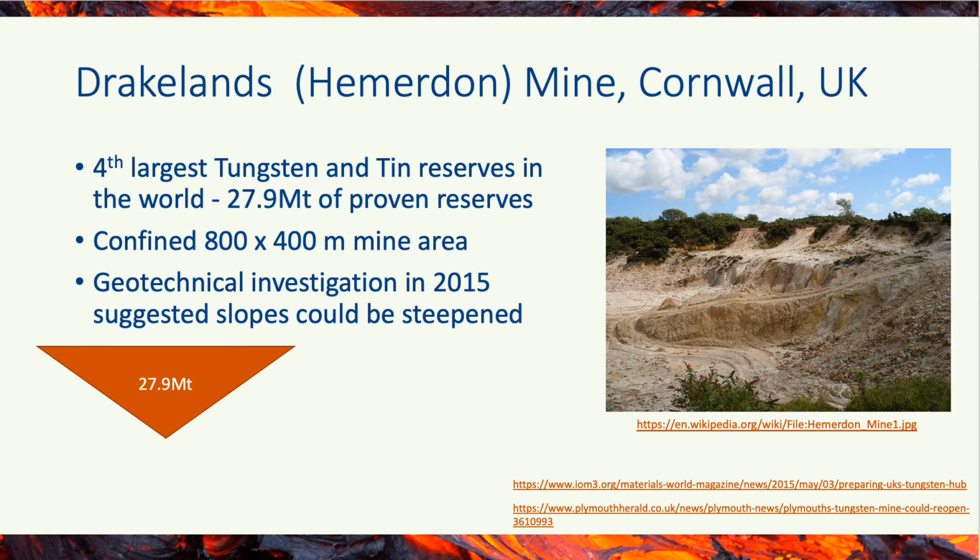So one of the things that was done to try and improve the extraction rate here was in 2015, a series of geotechnical tests were carried out, which were to basically analyze how strong the material that made up this quarry was. And the question was whether the slope that was being maintained at the moment, which was about 30 degrees on average, could be steepened.